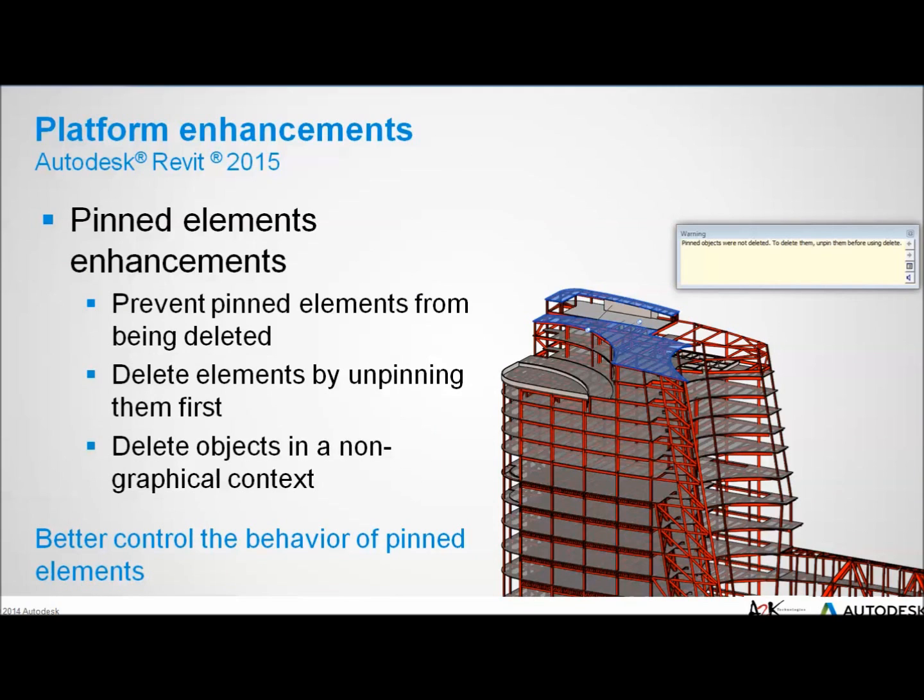Pinned elements, an enhanced option. Now it will not delete elements when elements have been pinned. In prior versions, the elements still deleted, only a warning was applied. So a combination of using the new 2015 feature and also the 2014 feature of being able to actually select pinned elements should now give you greater flexibility and understanding that not everything will be deleted accidentally.